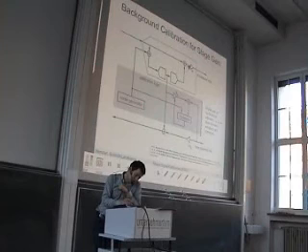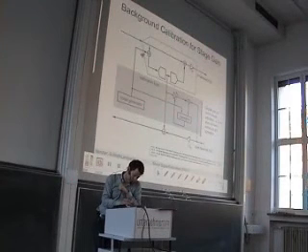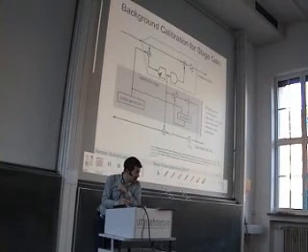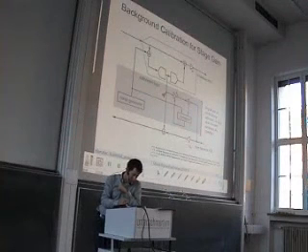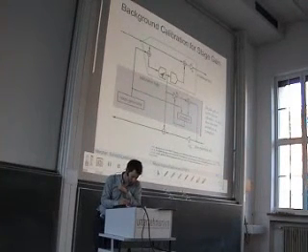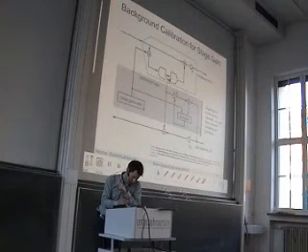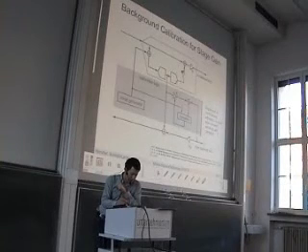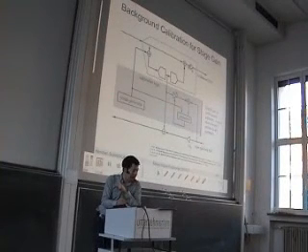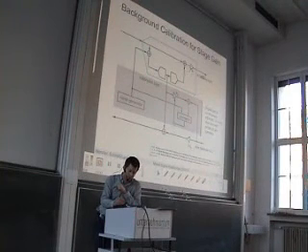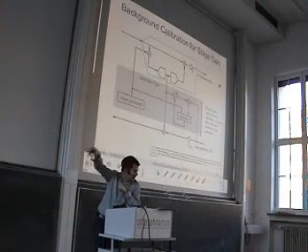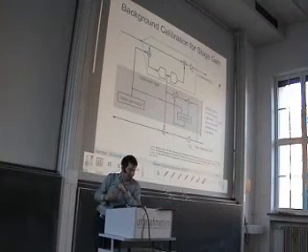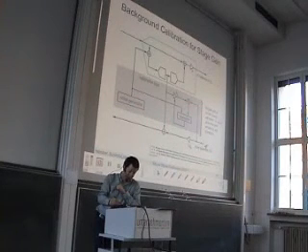What you can do is to inject a signal here, and this signal here is quantized in the ADC and becomes visible here. This signal is not only quantized by the ADC, but then it is also converted back into the analog domain by this DAC, passes here, is scaled by a factor of A, and then it goes through all other pipeline stages and through the backend ADC, and it comes back here.